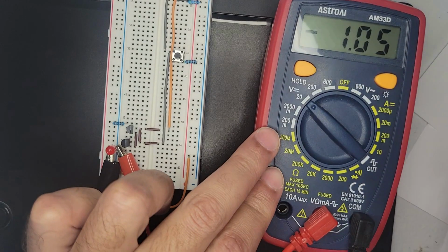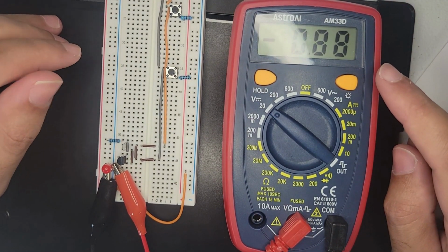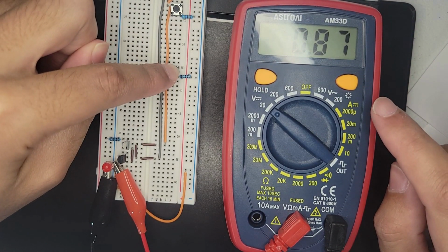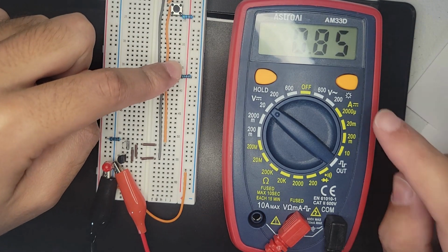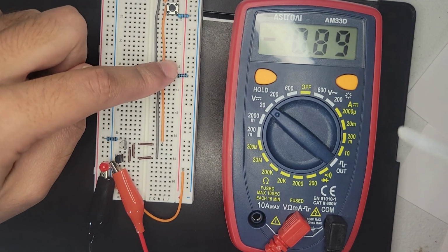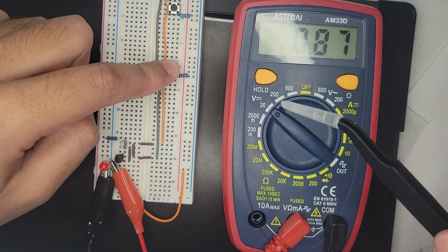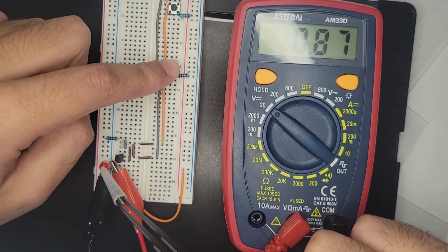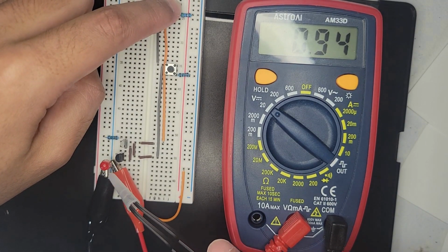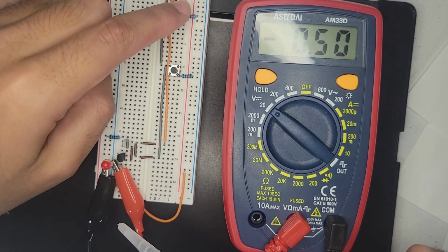And let's turn this to voltage. All right, so we have a pretty high negative number, 0.99. And if I press a button, then it goes to positive 0.8. As I recall, these should be 1.8 volts. So maybe what's happening is there's some kind of voltage leak or something like that that's preventing this guy from turning on. But the good thing is that he does receive voltage. And this guy, now it's 0.95. That's so weird. So he does receive voltage.